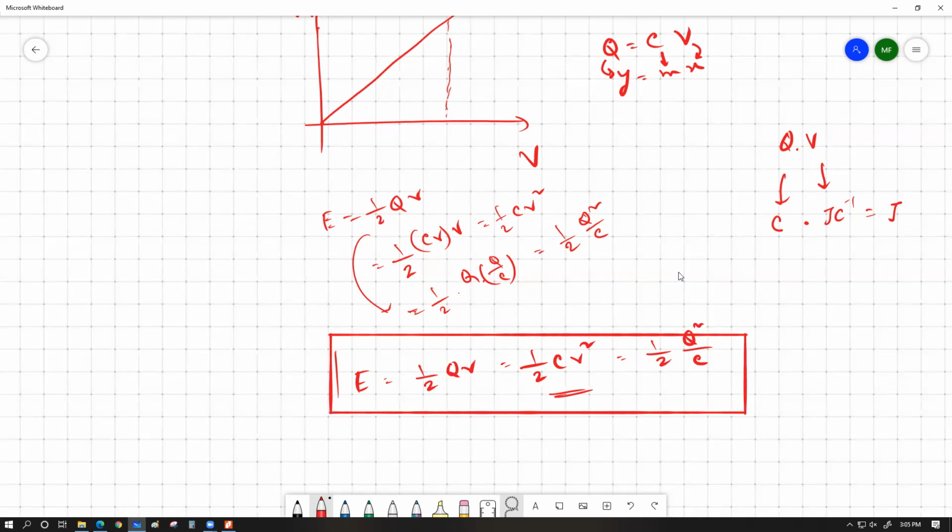So you can just read off from their body how much capacitance it has, or you can measure the capacitor value very easily using a multimeter as well. Standard digital multimeters can measure the capacitance of a capacitor very easily. And the voltage across a capacitor can be very easily measured using a voltmeter as well. So measuring or knowing this information for a capacitor is usually very simple compared to knowing exactly how much charge actually went into one of the plates of the capacitor.